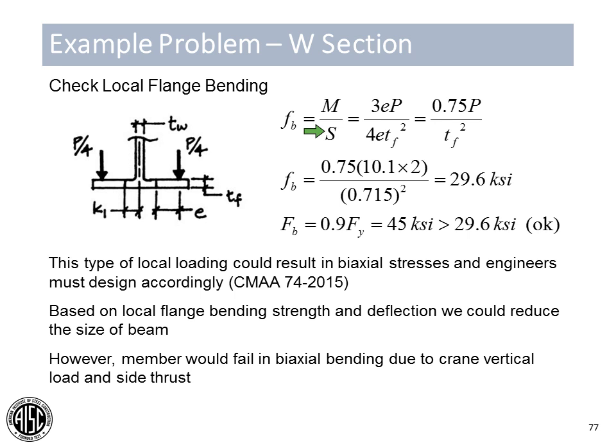Look at the local or the combined effects of the two loading applications and two flexural directions concurrently. So yes, it should be added, but it will not be added to the overall flexural stress of the beam. You'd have to look at the flange itself.